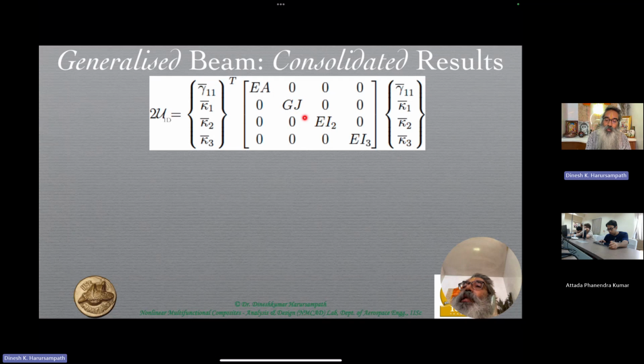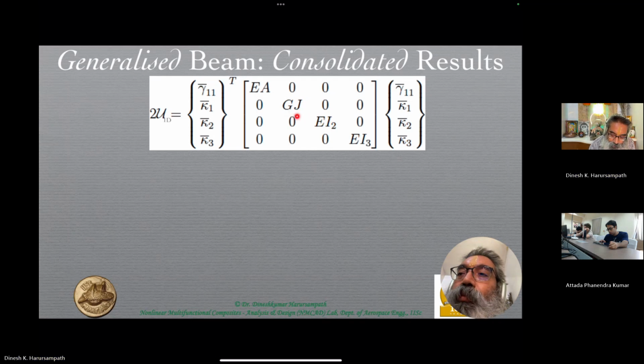Then the second slide that we saw today talked about the torsional member, the shaft, where the material property of interest is the shear modulus, and the property of interest as far as the geometry is concerned is the torsional constant, which happened to be IP, the polar moment of inertia, only for circular cross sections, solid or hollow, but not otherwise. And in most cases we are using rectangular box beams, so never use the polar moment of inertia there.